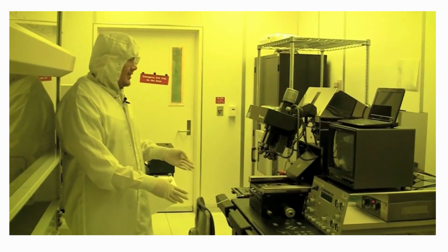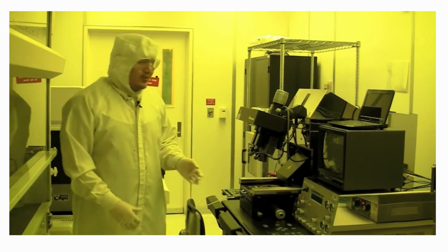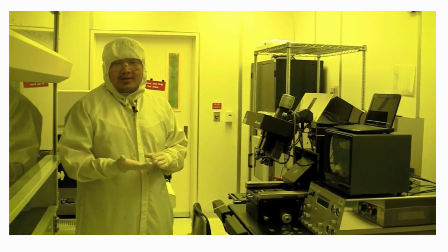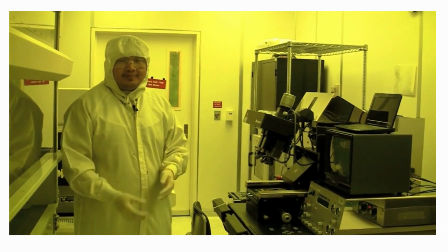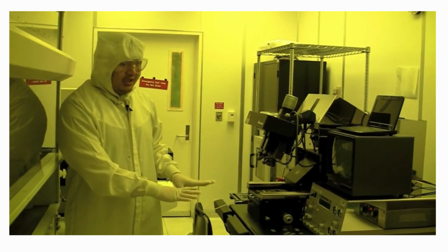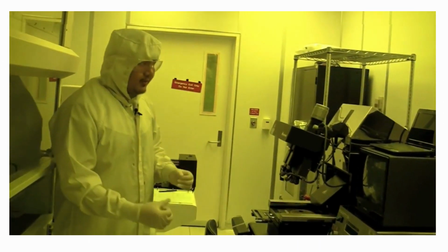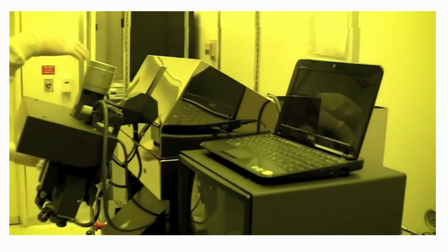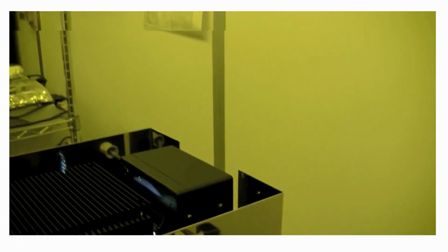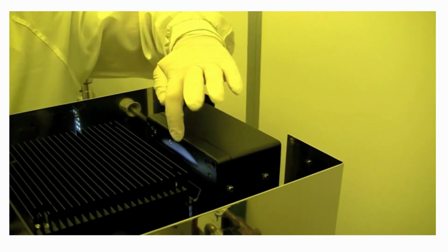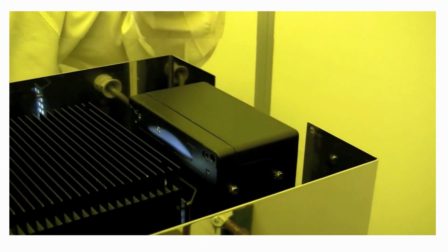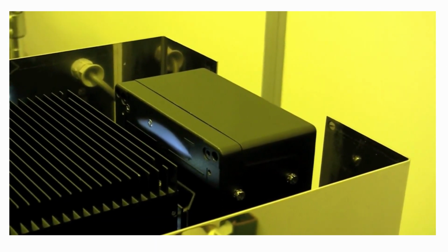This is the MA6. It's used to expose UV light to your substrate that has photoresist on it. So before we run the machine, the first thing we've got to do is make sure the light bulb is turned on or even not blown up. So we come out to the back, and you can see the light is turned on by the reflection here, or you can see the light glowing. So you know that the light bulb is on.